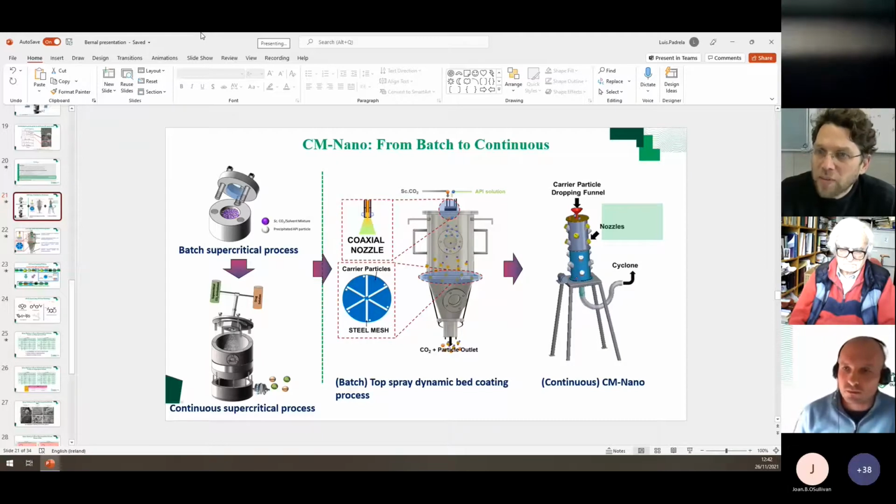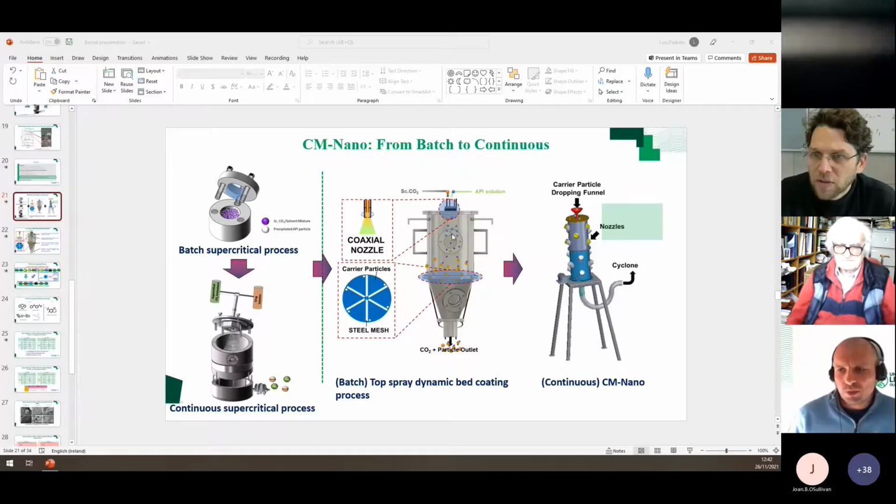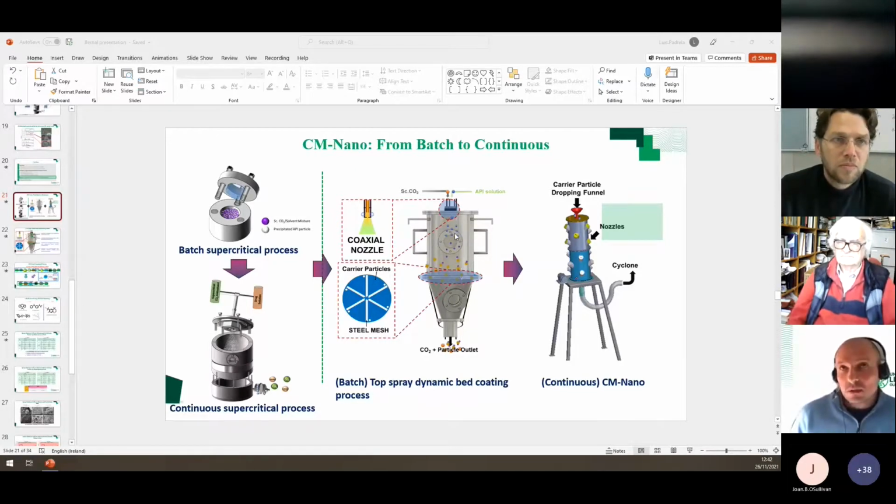One question from Ahmed. What is the average duration of the process? The supercritical spray drying depends on how much powder you produce. Typically, we are in the milligram scale for just using one nozzle. But if you are using the CM Nano, which is API onto excipients, it can take maybe a couple of hours because at the end you have excipient and API. So we can produce about 18 grams every 2 hours, if I'm correct, of API and excipient there.